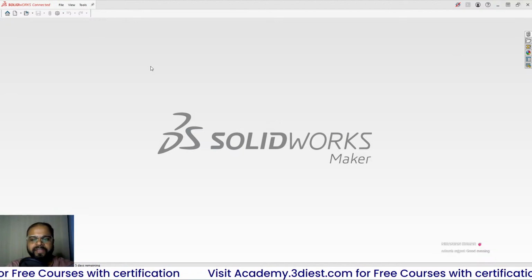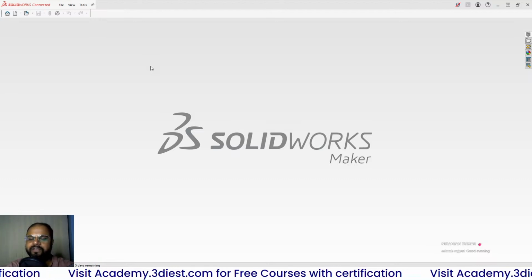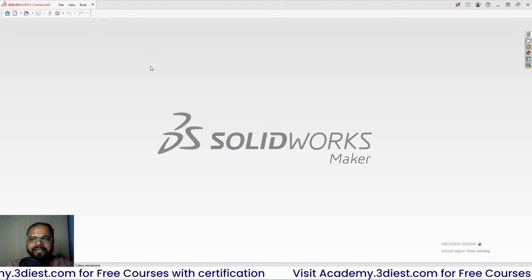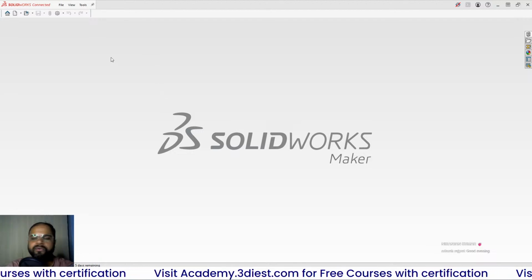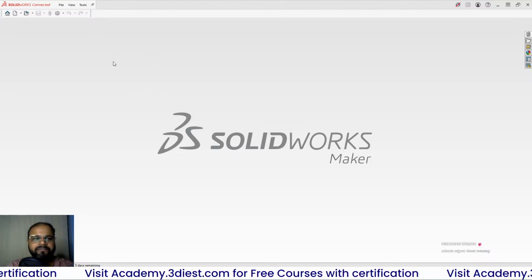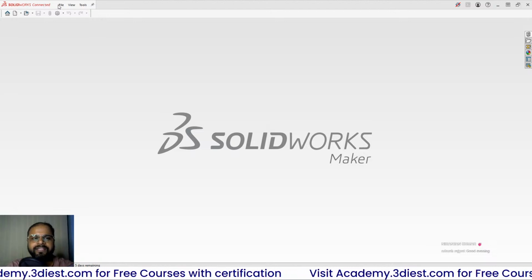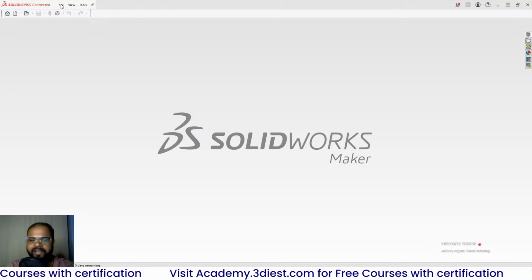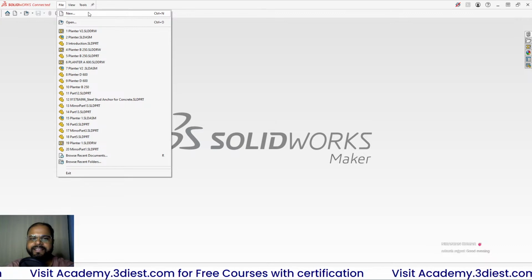Okay, so there are 3 ways you can launch a part file inside SolidWorks. If you want to create a new design, a new part, there are 3 ways you can launch the new file. The first way: if you go to the top over here, you will see a category that says File. If I click on it, here you can see it says New, right?